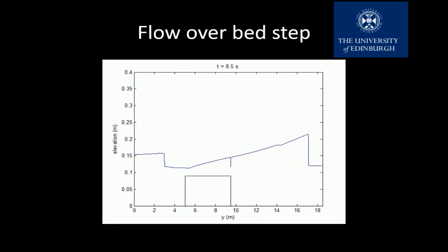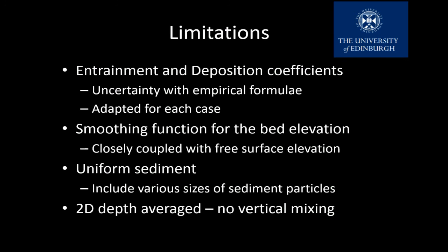What happens in the dam break is that you have these hydraulic jumps which develop, but at the same time you have reflections from the side walls, reflecting the water into the center. You have these hydraulic jumps developing because of the interaction over the bed, and then you get this really complex flow pattern. So I'll just wrap it up.